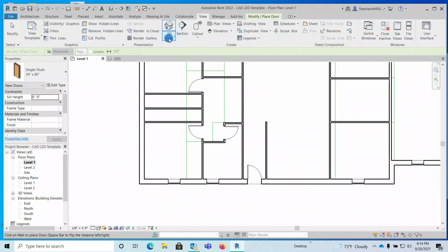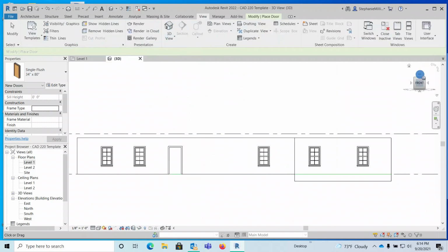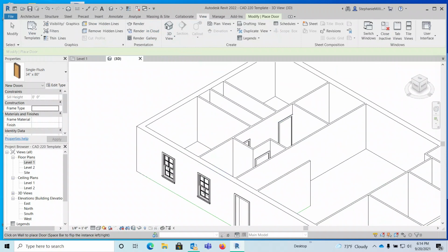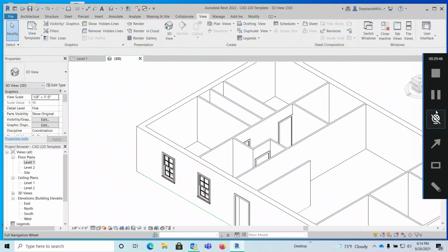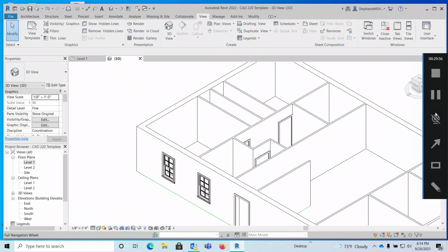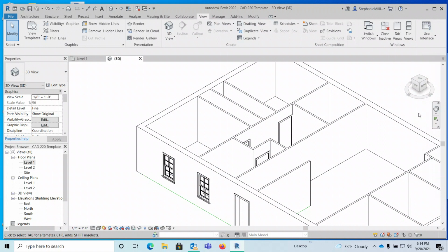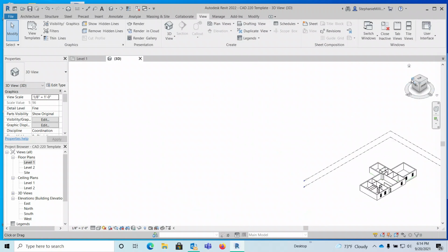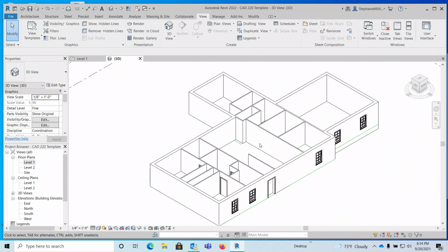So you just kind of start adding each of those features. And again, just every now and then, go back to 3D view, kind of look at it from that southwest isometric perspective, or use your pans and zooms and the orbit feature. So there is an orbit feature here. Since I'm not having a good time getting this thing to work, I've got too many icons that pop up. Use your orbit feature, or again, just keep looking at this thing from different angles. Do a lot of inspecting to see if you like how that's going to actually look. Because the great thing about this is you can also do walkthroughs later. So there are lots more things for us to still do and learn with this, but that should at least get you started on this assignment.